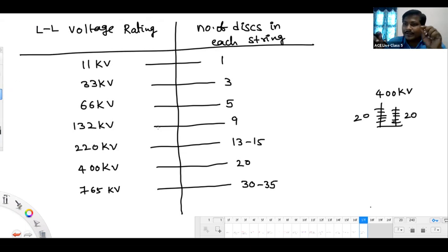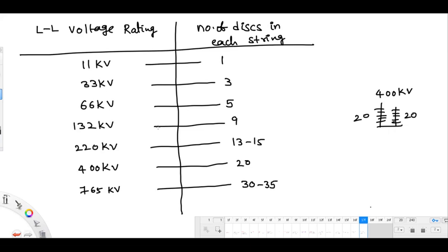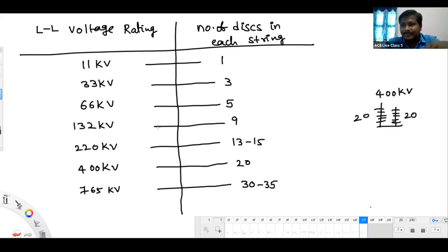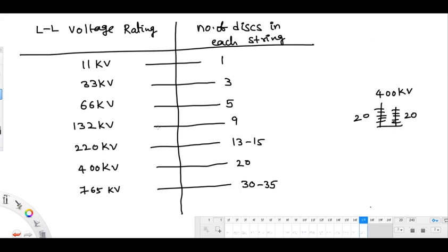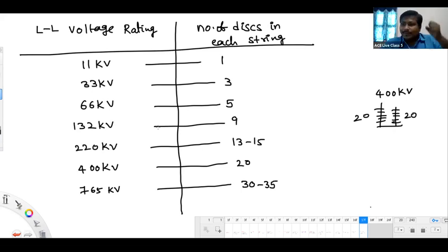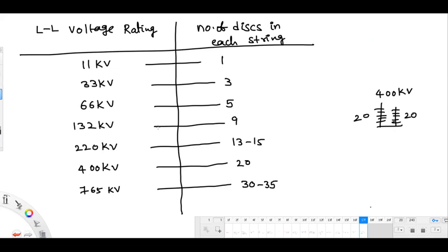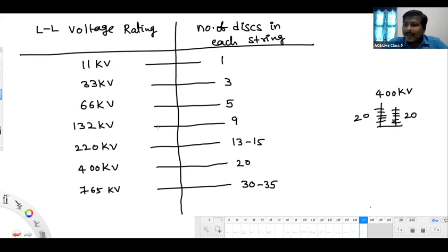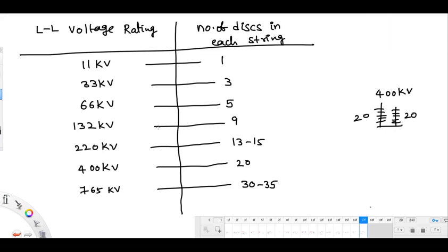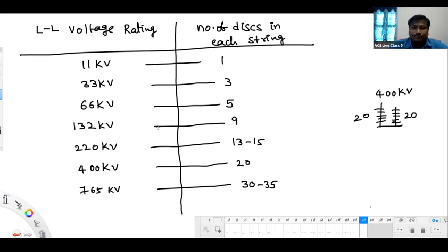In the Schering bridge, you will be keeping the unknown capacitance, right? Yes, sir. The 2 terminals will come out from the Schering bridge, across which you should keep the unknown capacitance. One terminal we keep to the sheath, the other one we keep to the bunch of 3 cores. That will give the capacitance value. But it's not a 3-phase cable operation there. That's why I have not written ABC, I have written only 1, 2, 3. I don't know whether you have cleared or not. Yes, sir, clear. Thank you, sir. Any more doubt here? No, sir.